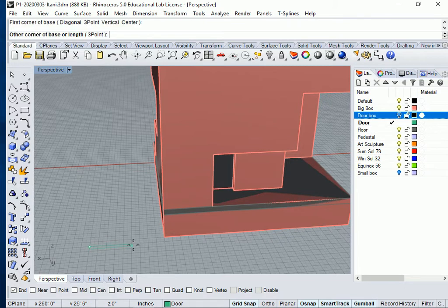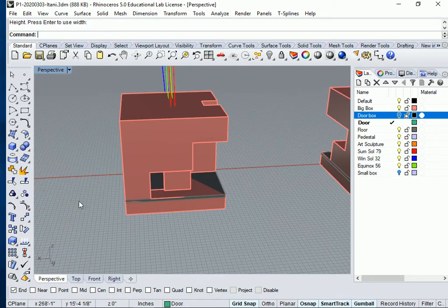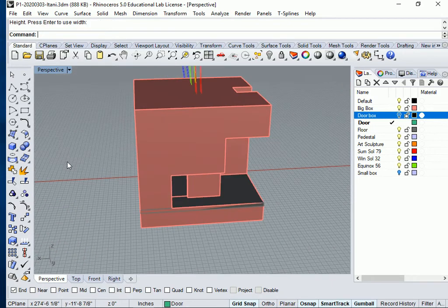And let's make the door maybe, let's see. Our door is going to be 7.0. So click at 7 feet, comma, and let's say the other direction is 2 inches. Press enter. And let's give it a height. What is our height going to be? Oh, we made it sideways actually. We're going at 3.6, aren't we?